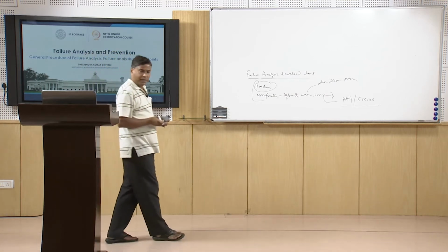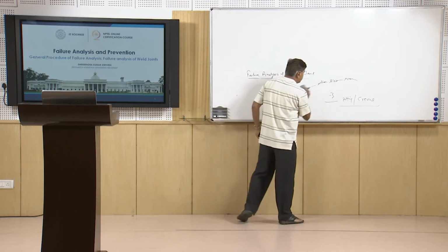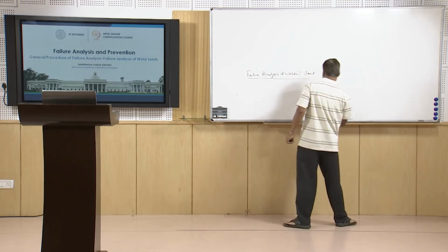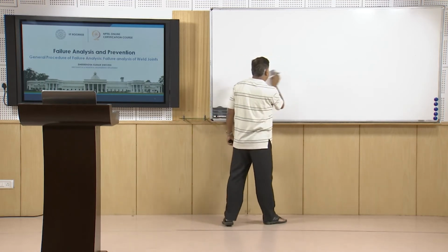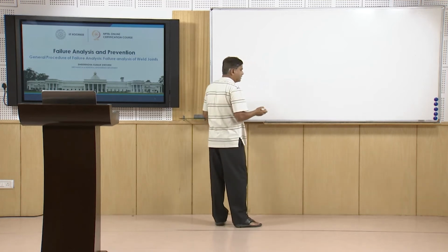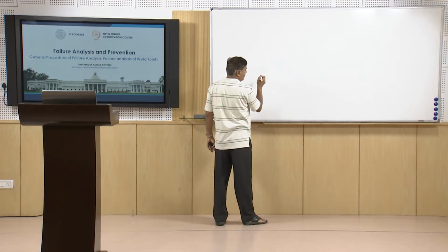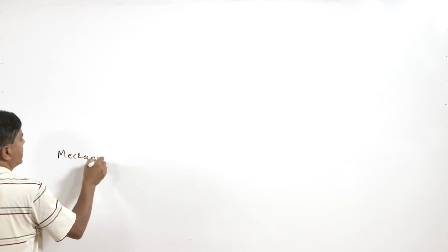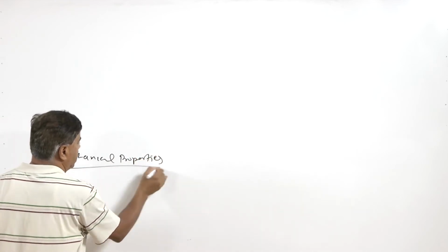As far as the analysis of the weld metal, base metal and heat affected zone is concerned, if the failure is occurring from a particular location, then there would be some reason behind the failure occurring from that location. Under the given external load conditions or service conditions, as per the broader mechanism of failure, there may be a deficiency of mechanical properties, especially with regard to metallurgical failures.